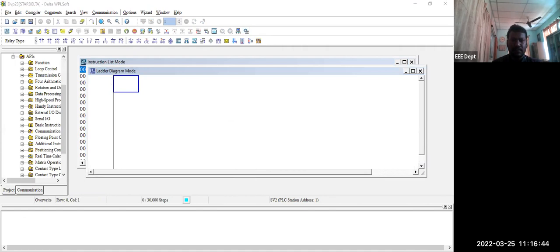So coming to the star delta starter, here we see how to start a 3-phase induction motor using a star delta starter, which is a very common type of starter. It is used extensively compared to other starting methods. The star delta starter is used for a squirrel cage induction motor designed to run normally on a delta connected stator winding. So here we start the motor in the starting condition and run it in the running condition by using the star delta starter.